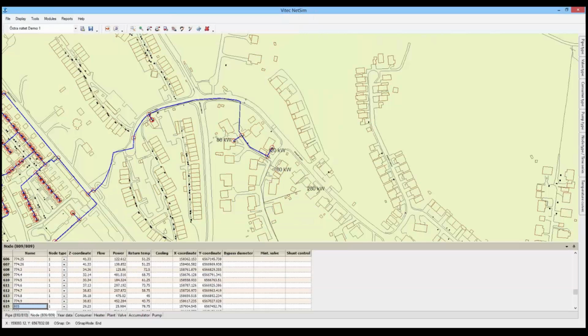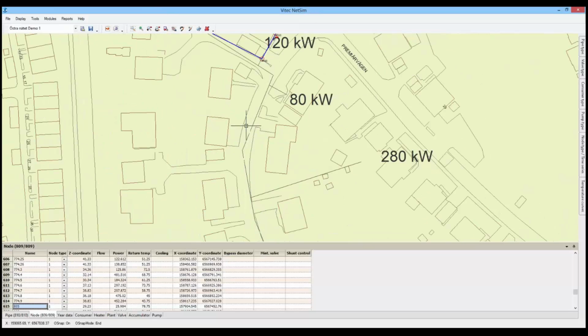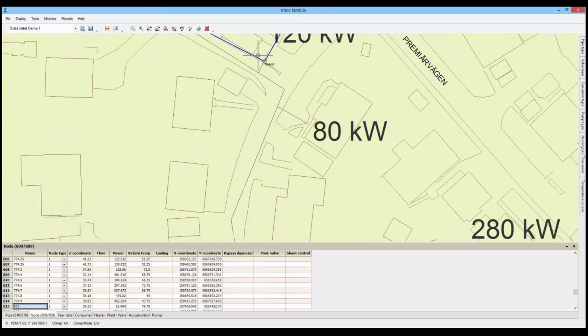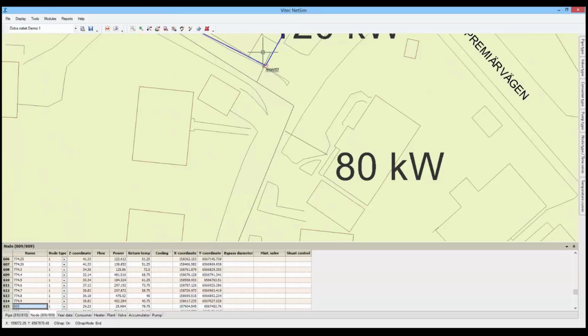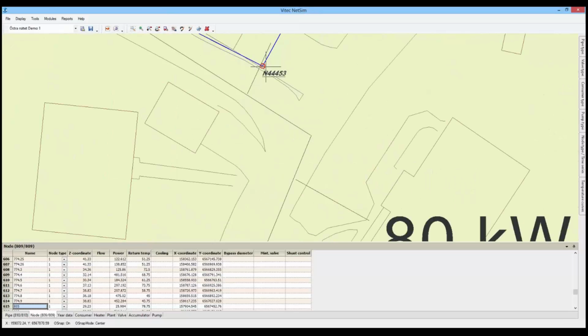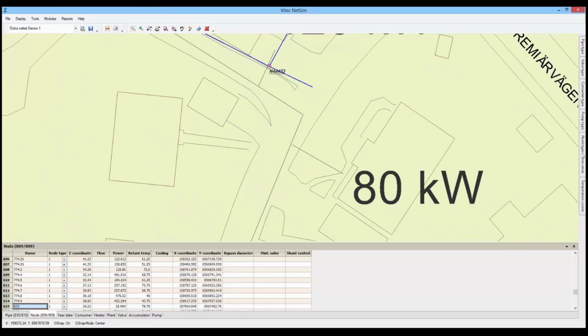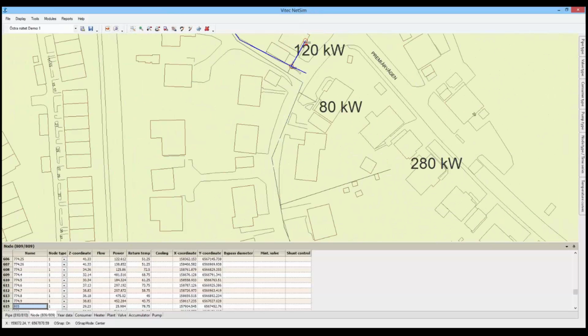Open up like that, and here we have some pipes. So let's make a new pipe. Draw pipe, it's a command. When you take the cursor to a node, and the node hits, you have connect, and then you just click where the pipe is going, like that.